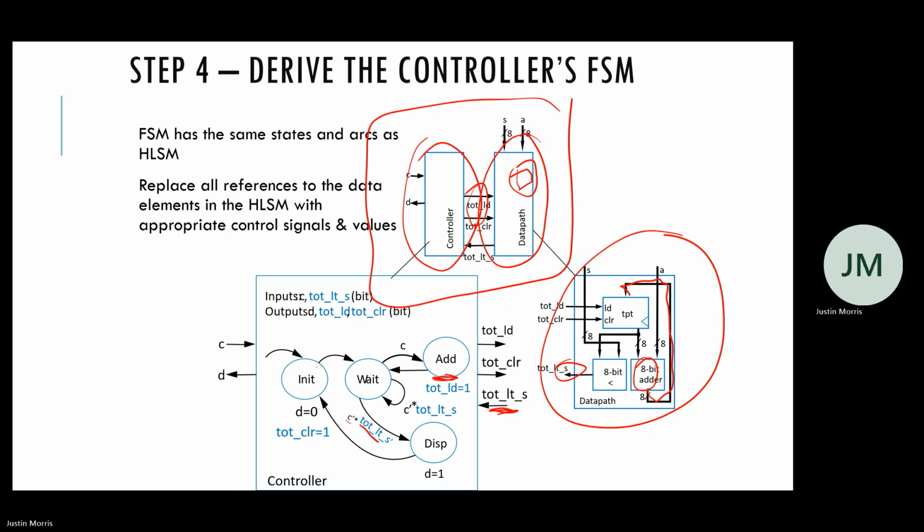So all of these signals, you would determine what signal you would need. Do I need to be able to clear? Do I need to be able to load? If it's always enabled, I don't really need to have an enable, right? But almost certainly I always need a clear, because if I don't have a clear, it's junk in the beginning, right?